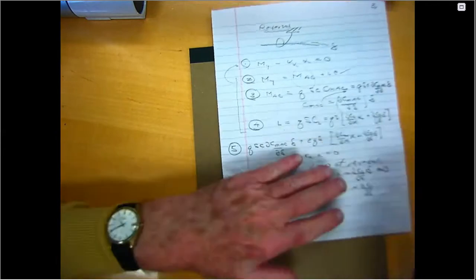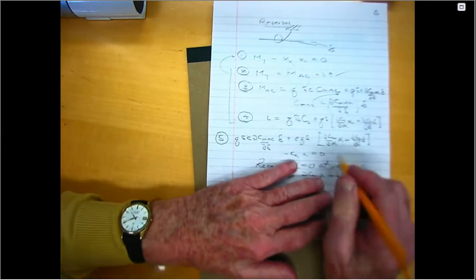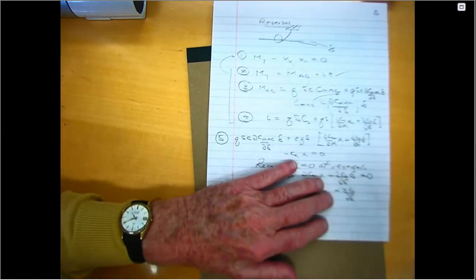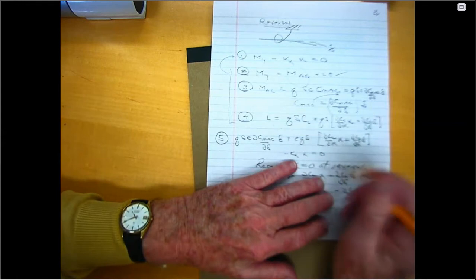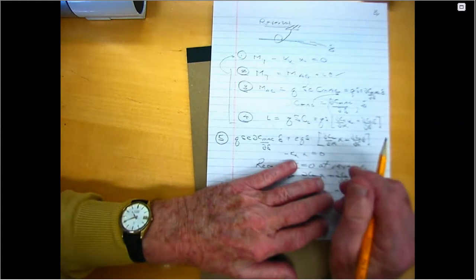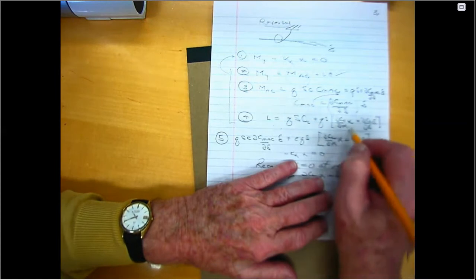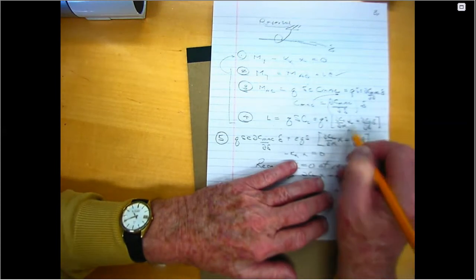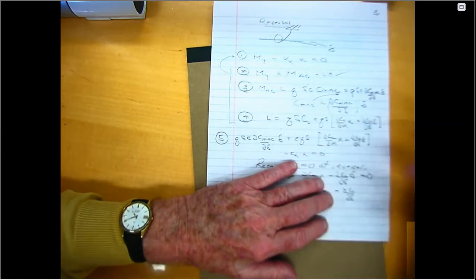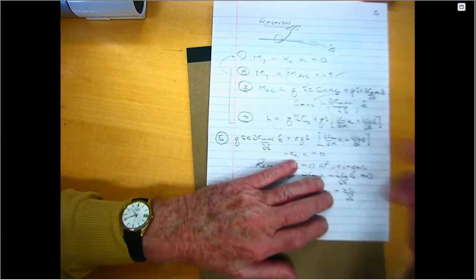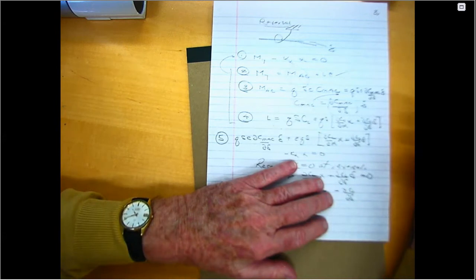Let's go back to equation 5. Equation 5 is an equation which says, you tell me what delta is, and I can compute alpha from this equation, right? Then I can take that delta and that alpha and put it in the equation for lift, and I'll have that expression for lift. Give me a delta, and that's what the lift is. Then I would look at that equation and say, by the way, can the lift ever be 0? And the answer is yes.